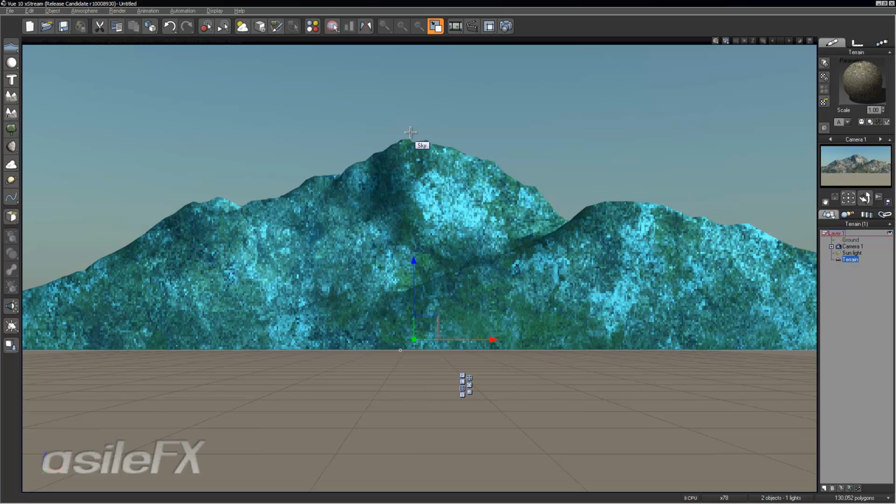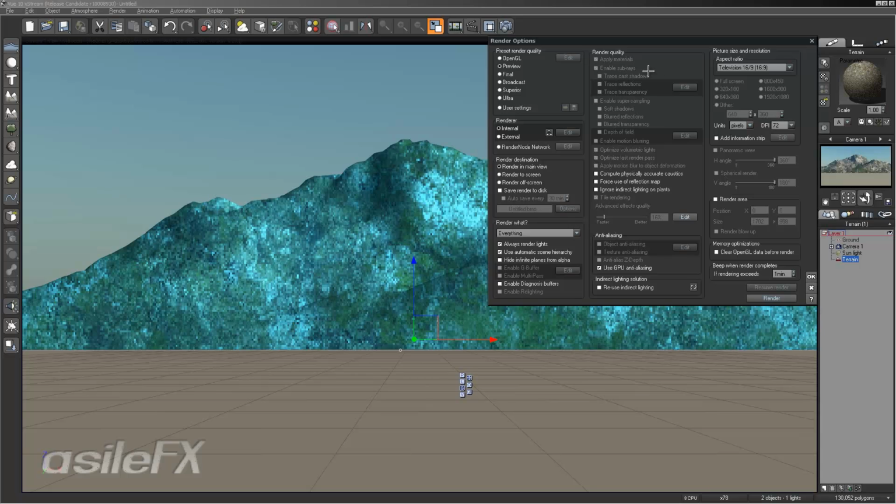And one thing I didn't do is set the aspect ratio. So if you need to adjust this to fit the aspect of the camera and the render output, take a look at your render options. And in order to get the aspect ratio, you just divide the width by the height.